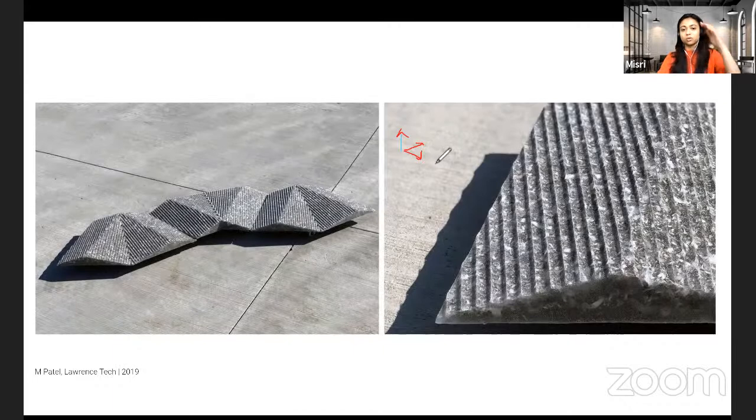All your contours would be generated, and we'll use that to create lines in X, Y, and Z planes, versus what happens with 6-axis, where this geometry could potentially be milled. If you imagine this to be the tool head, it would move along the geometry in something like this fashion. You're not restricted by X, Y, and Z, but with 6 axes you could do that, instead of a 3-axis milling machine, which can only do this.